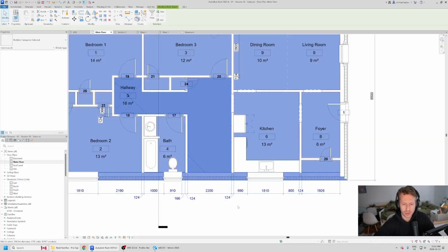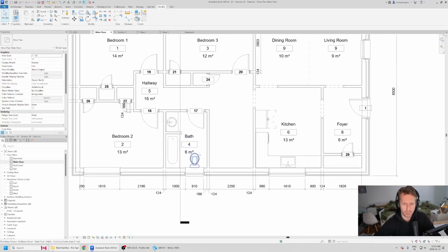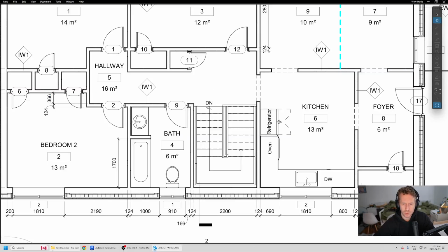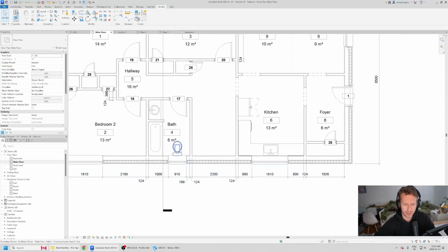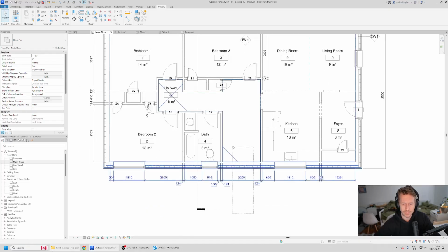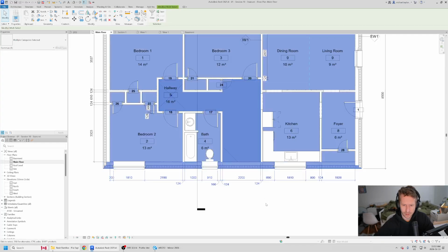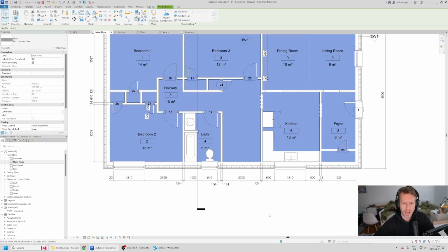So the easiest way to do that is to find our floor, and then we're going to cut a hole in the profile. So for me, I just want to create a hole where our stair is going to go roughly, and then we can adjust it once the stair is in action here. So let's find our floor. Fastest way to do that is to hold my left mouse button and do a crosshair select backwards, up and to the left, filter, check none, go to floors, click floors on, and now I've got my floor selected.